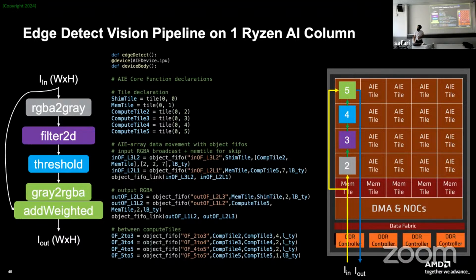Those channels in the network, you can get in two ways. I didn't explain it, but there are switch boxes in the interconnect network. You can use a circuit switch mode, in which you directly set up communication from one point to another. You have on average 4 channels in one direction and the other direction. So you can run out in the end as well. It's not game over, because you can also use packet communication. Either you as a designer or the tool can decide, or a combination.